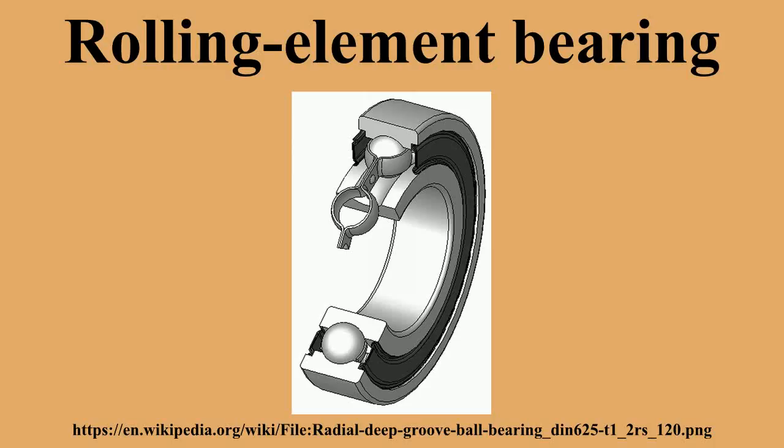Roller element bearings for a shaft use bearing balls in a groove designed to recirculate them from one end to the other as the bearing moves. As such, they're called linear ball bearings or recirculating bearings. Constraints and trade-offs. All parts of a bearing are subject to many design constraints. For example, the inner and outer races are often complex shapes, making them difficult to manufacture. Balls and rollers, though simpler in shape, have small radii, since they bend sharply where they run on the races. The bearings are prone to fatigue.